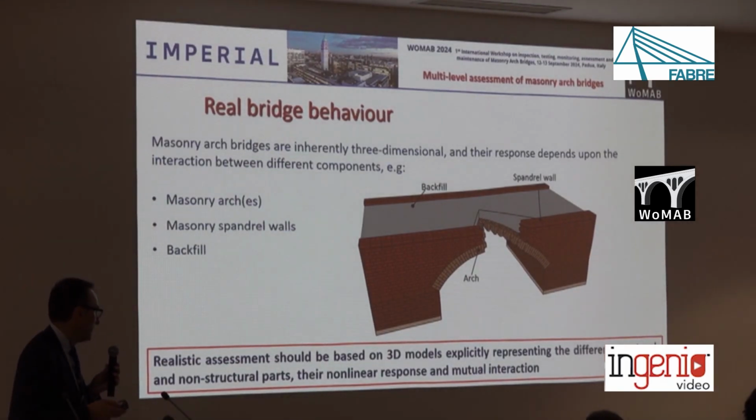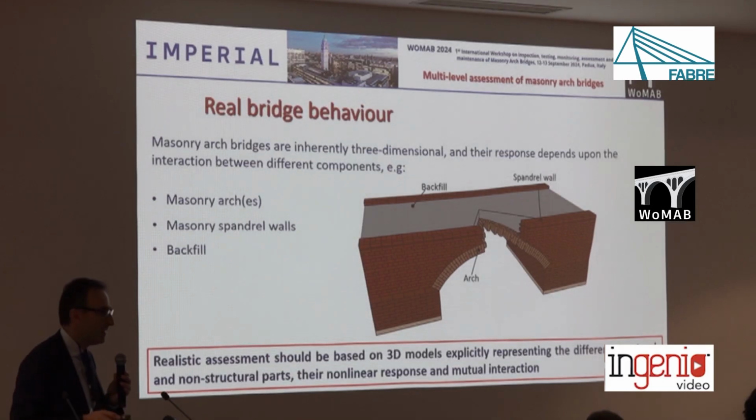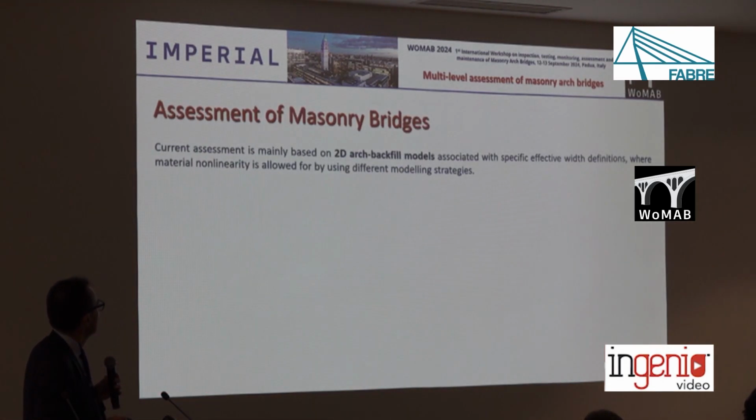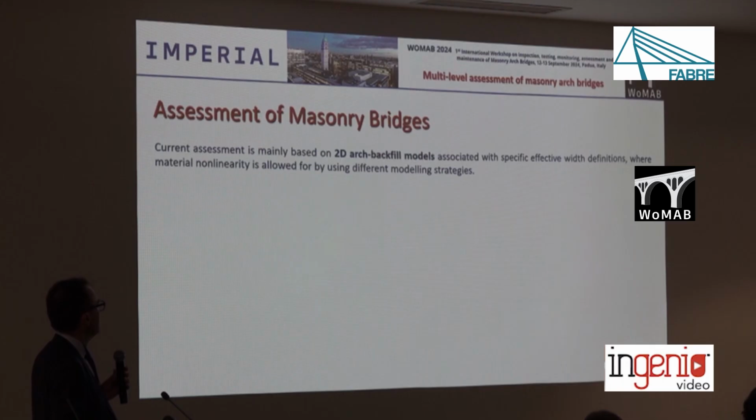To achieve an accurate response prediction, we should consider the use of 3D models, explicitly take into account the different structural and non-structural parts, including their nonlinear interaction. So current assessment, though, is typically based on simplistic methods for different reasons, for practicality, for computational cost.